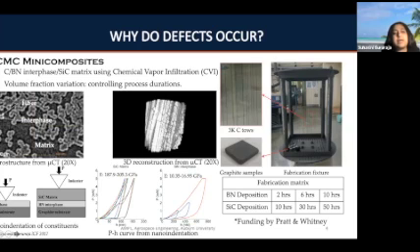The other aspect is things like fiber clustering that you see. Invariably, your distribution of the fibers at the microstructure level is not uniform, and that has a huge effect as far as damage predictions go. If you have two fibers that are close to each other, the volume of material in between the two fibers would be the points where damage initiation gets triggered, and that would grow as you go across the length scales. So those are some of the open questions that we are interested in understanding.